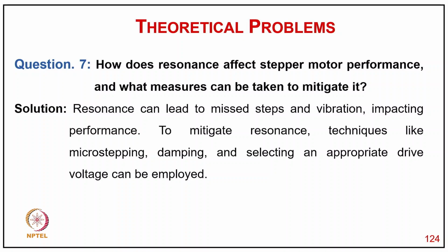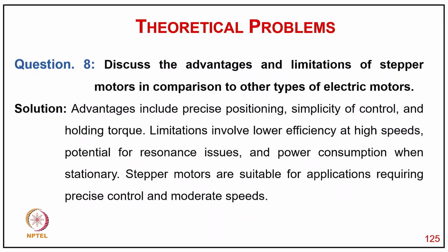How does resonance affect the stepper motor performance, and what measures can be taken to mitigate it? Resonance can lead to missed steps and vibration, impacting performance. And to mitigate resonance, techniques like microstepping, damping, and selecting an appropriate drive voltage can be employed.